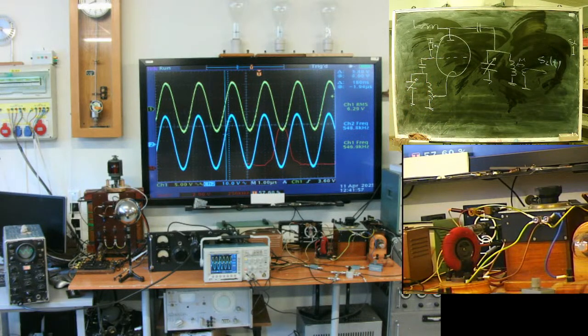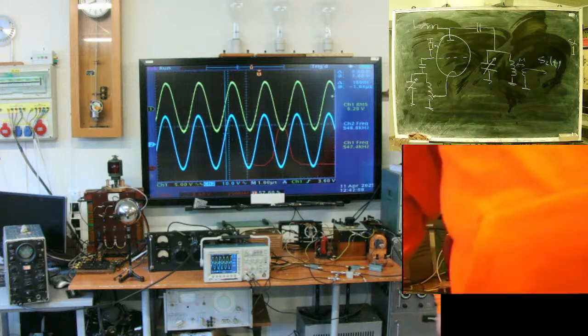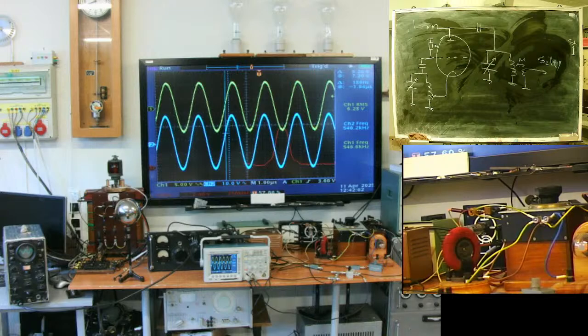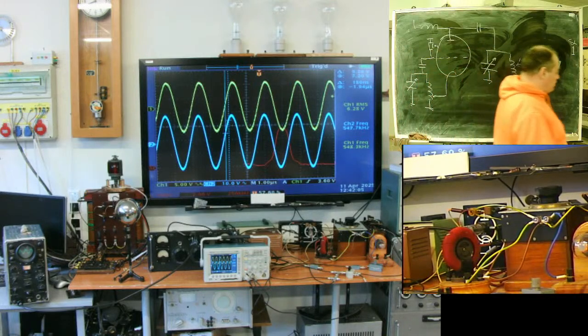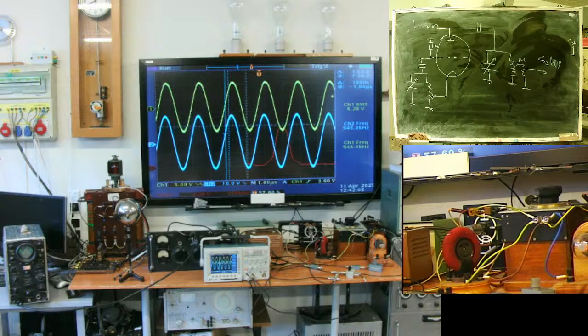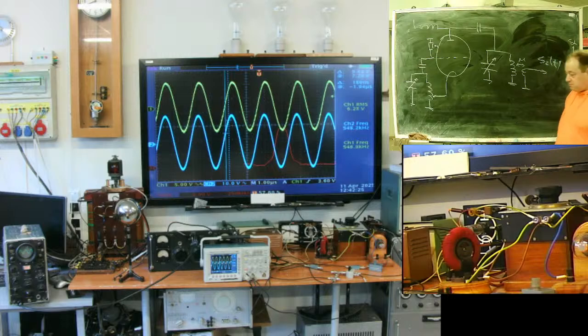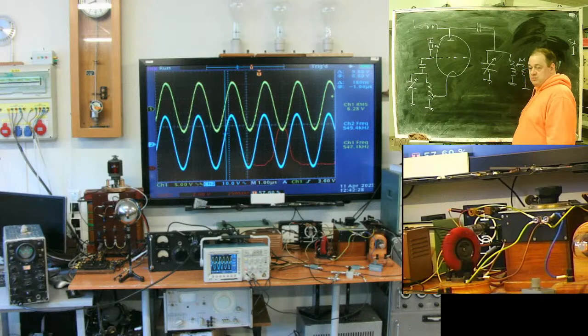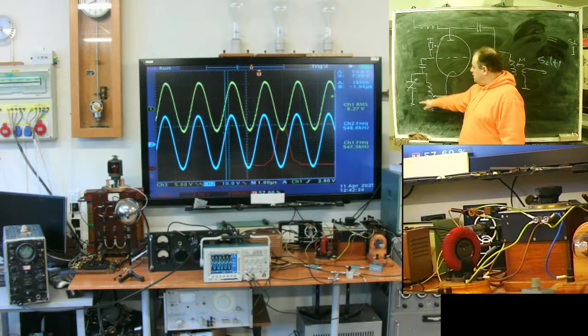The idea: when you have only one selective circuit in your generator and it's coupled with a load, resistance will decrease its quality. This means the frequency will not be so stable. To increase the quality of the signal, one way is to use, in sequence, a pair of resonant circuits. They should be adjusted to the same frequency. This part here is positive feedback.